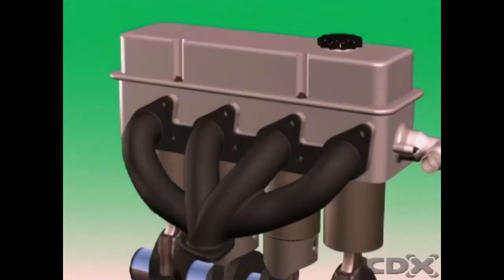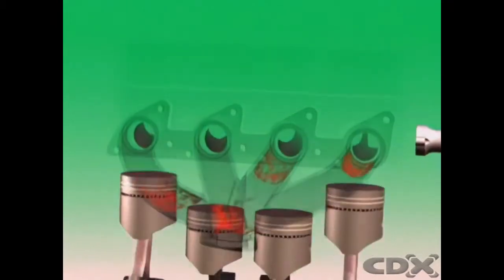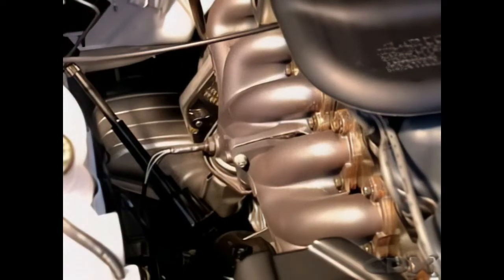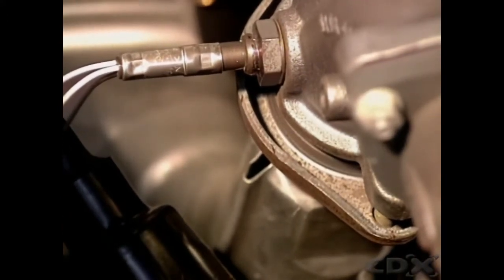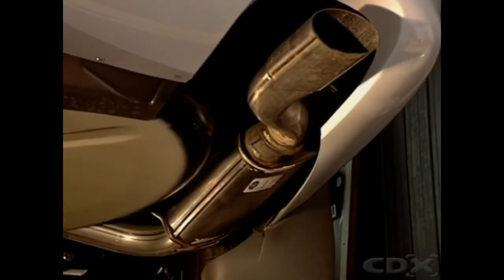In this simplified model, burned gases exit the cylinder through the exhaust port and pass into the exhaust manifold. The first pipe is usually called the engine pipe. It's connected to the outlet of the manifold, which carries the exhaust gases to the muffler, which reduces exhaust noise. Exhaust gases are then discharged through a tailpipe, usually at the rear, or sometimes above the vehicle.